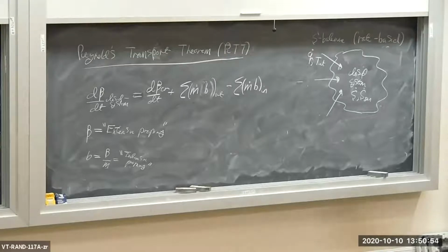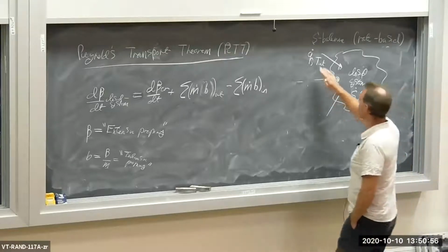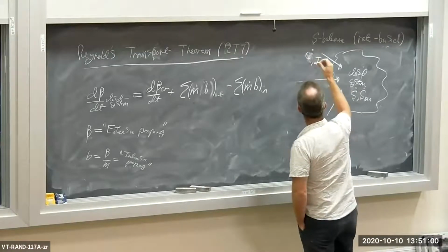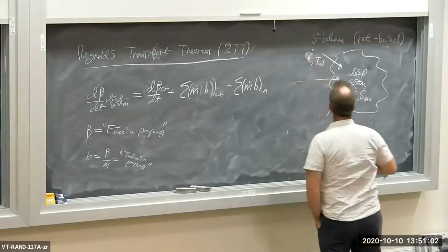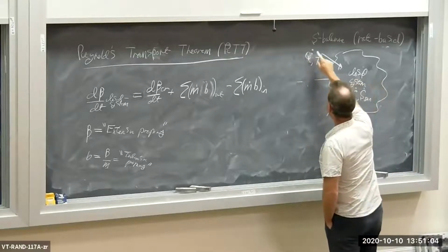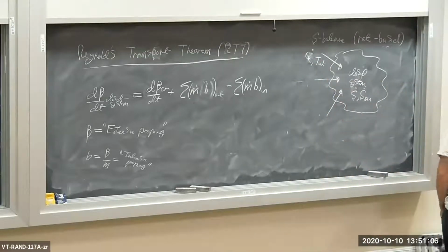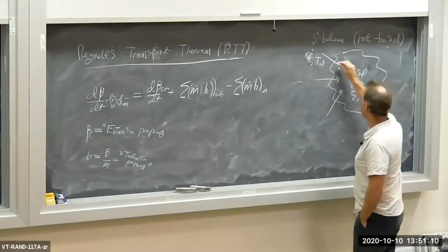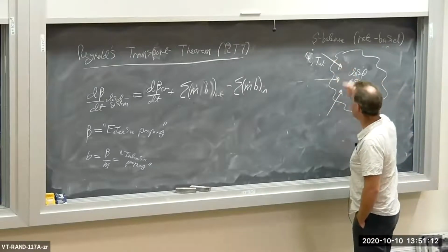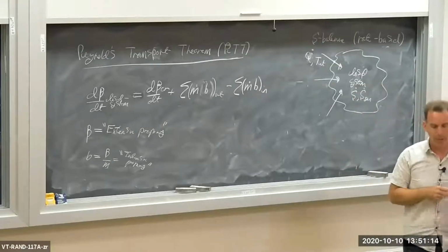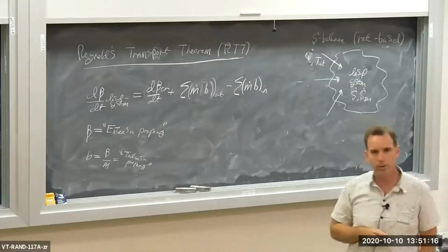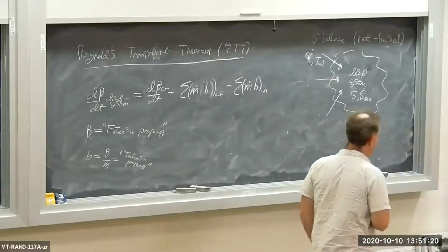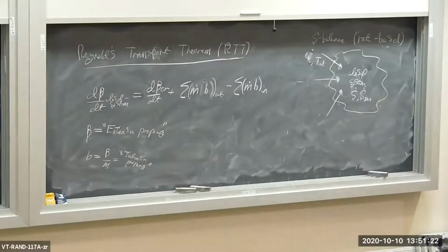So here we have the closed system receiving various heat interactions. So we have Q dot, T interaction. So you put a thermometer right here, and that's your interaction temperature right there where the heat flow crosses the system boundary. Q dot over T interaction is your entropy flow into the system.